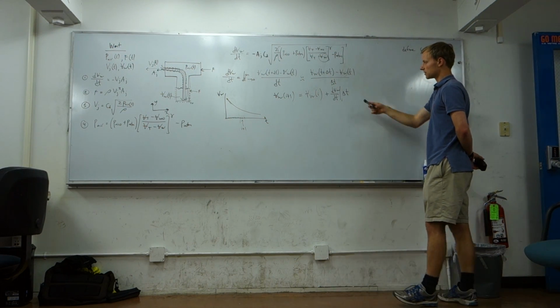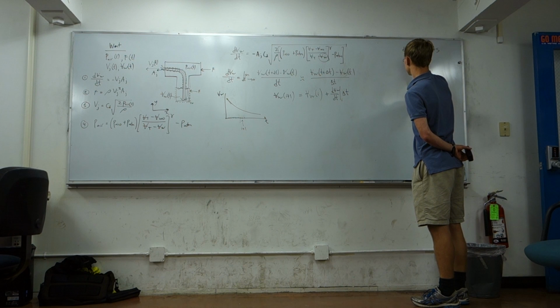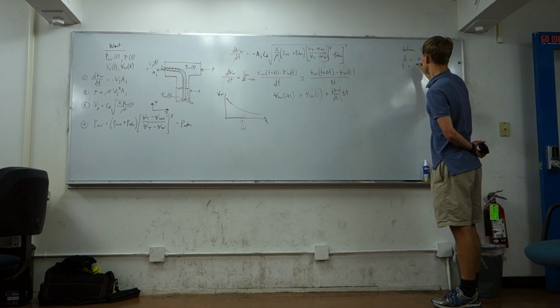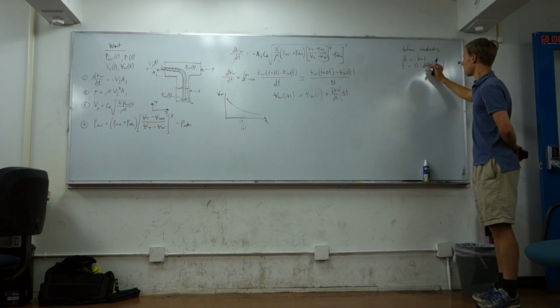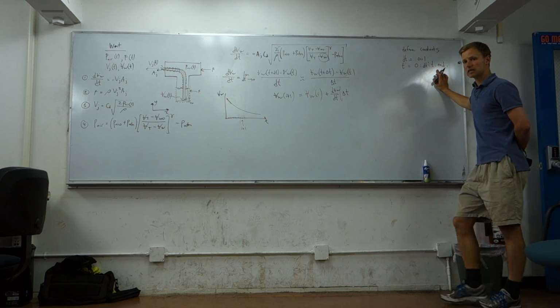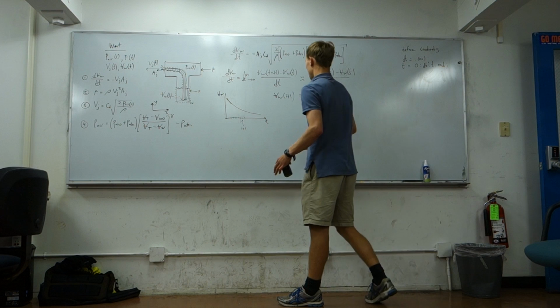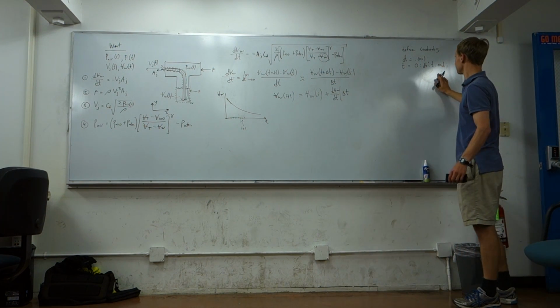Then we have to create our whole time domain here. But before we do that, we need to decide what our time increment is going to be. I'm going to say our time increment dt is 0.001, arbitrary. And I'll create our time vector here, t, which will be a vector from 0 at increments of dt all the way to t end. And t end is actually a known quantity which is going to come from our experimental data. It's just the time for this whole experiment to happen. It's t underscore n in the Matlab script currently, but you should double check what that's going to be.